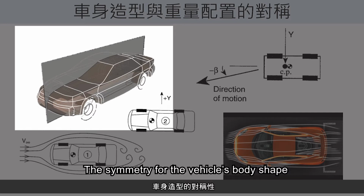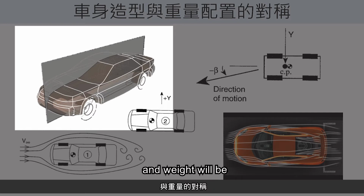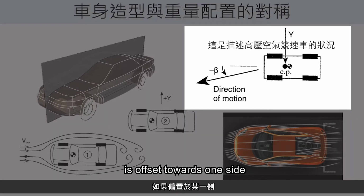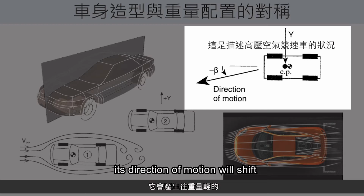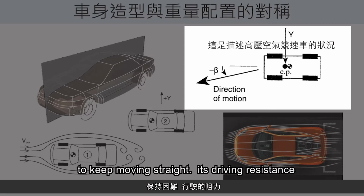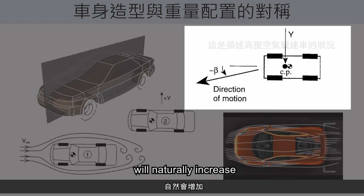The symmetry of the vehicle's body shape and weight will be a key priority for us to consider. For example, if the vehicle's center of gravity is offset towards one side, its direction of motion will shift towards the lighter weight side, so it will be harder for the vehicle to keep moving straight. Its moving resistance will increase.